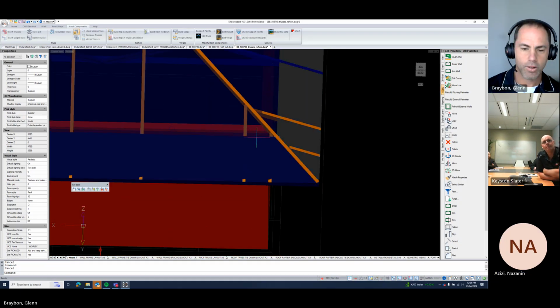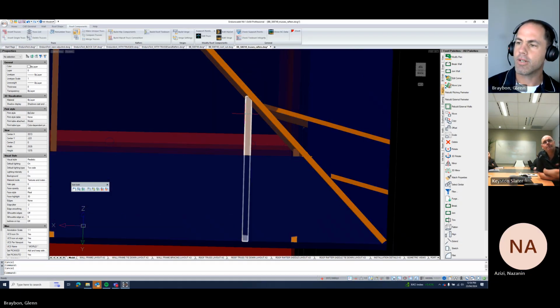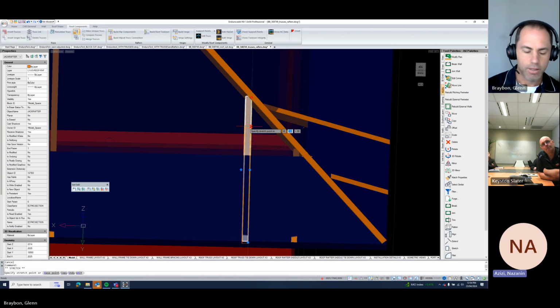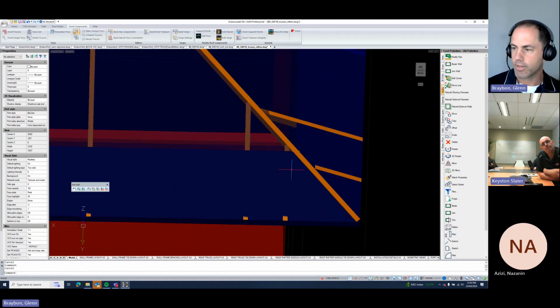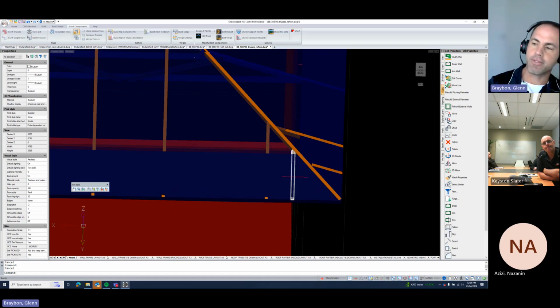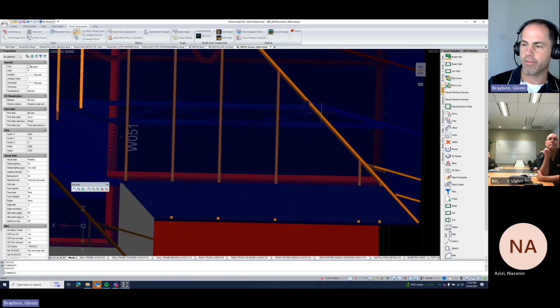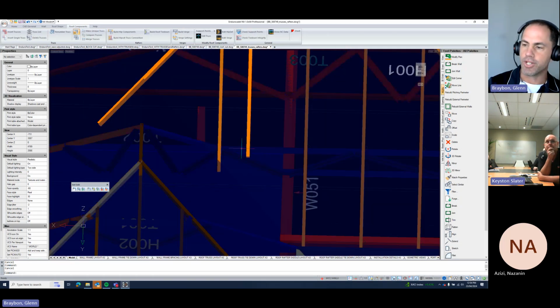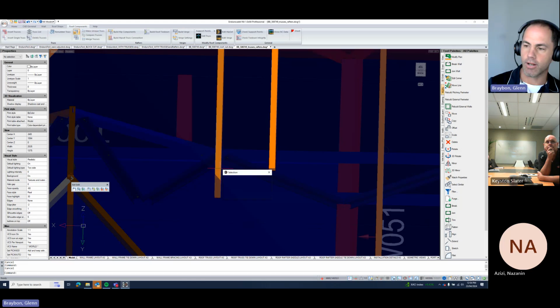Are we going to be able to use that one where we can just move it like that, like stretch it from that grip point? Yes, you can use it. I like that one. Stretch is a great spot. If you're stretching it, it's going to detect the hip and create the bent tab connection. No, you have to move. That's what I mean. It's not good when you're stretching it from a hip, but maybe if you're in a valley and you're not so worried about the actual endpoint. That's a bit long there.